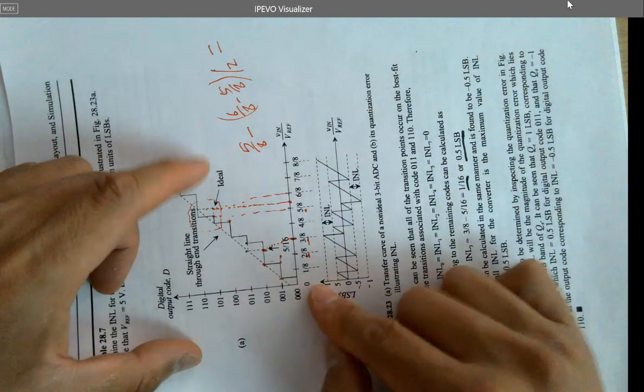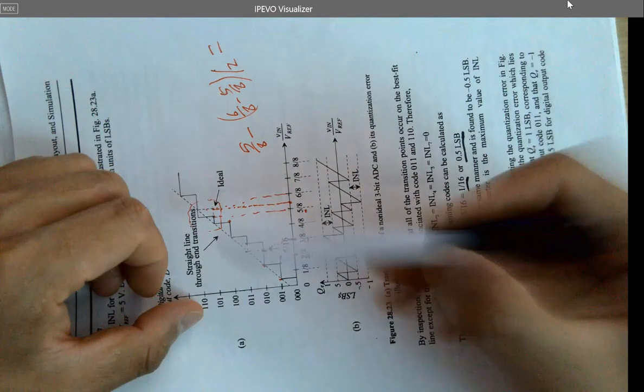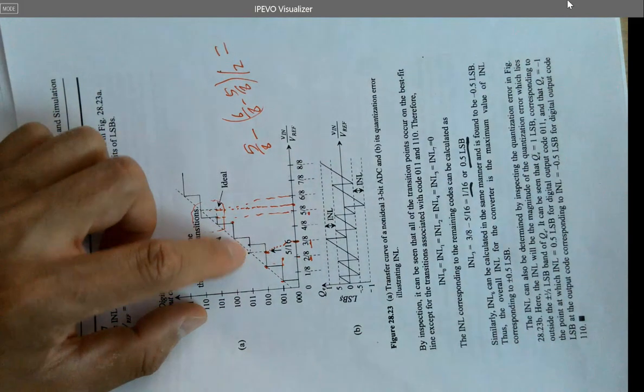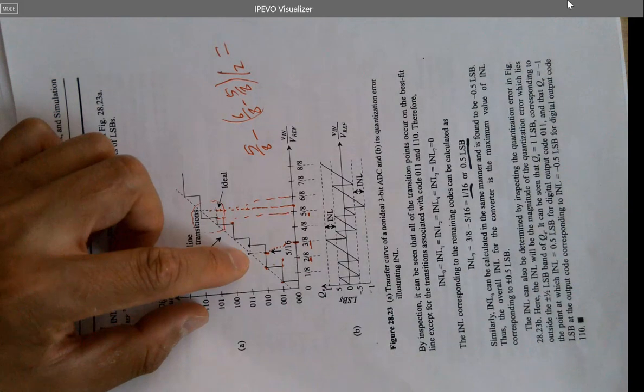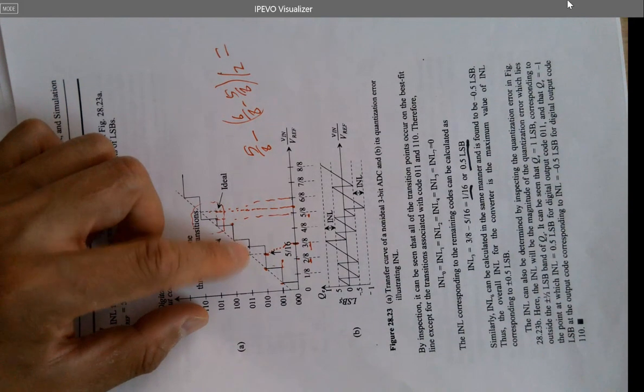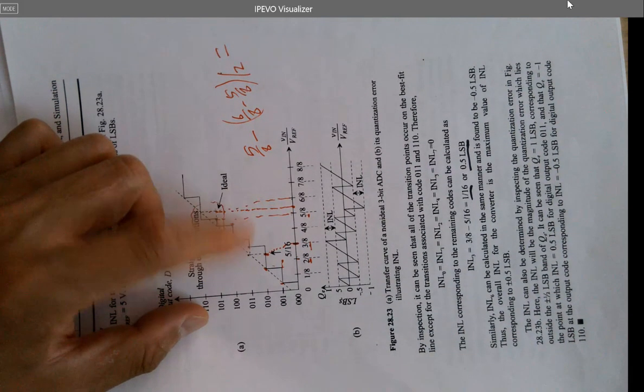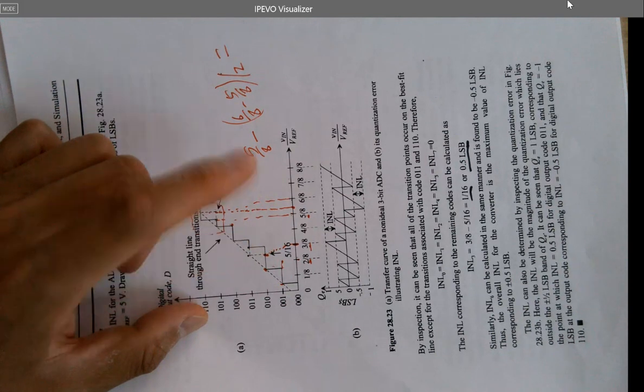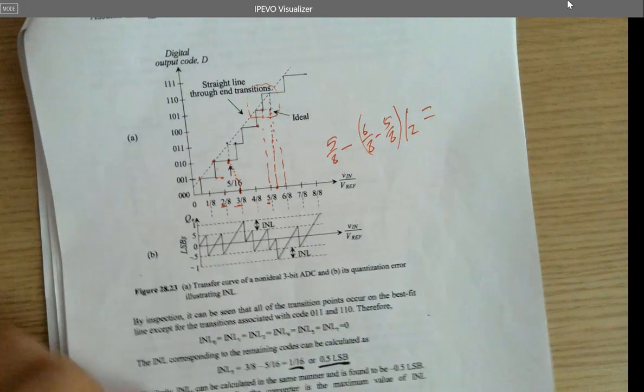So assume this axis is y, okay? And this point here is definitely higher than this one. Just do the subtraction, use the higher one minus the lower one and get the difference of the heights. So that's the INL. It's an easier way to calculate it. The textbook may show a different way to do it, but that's how you get all the correct values.